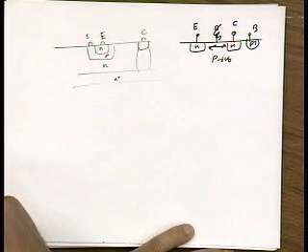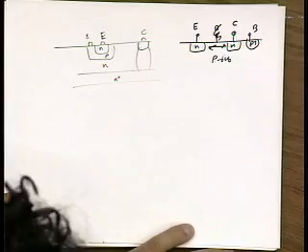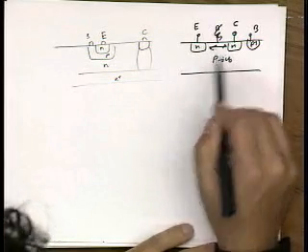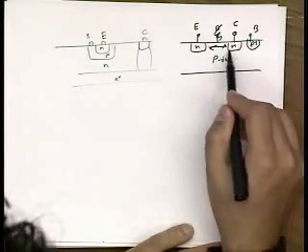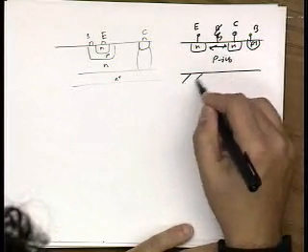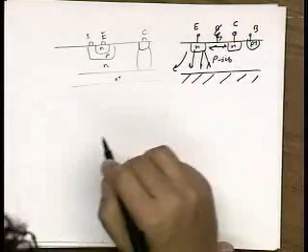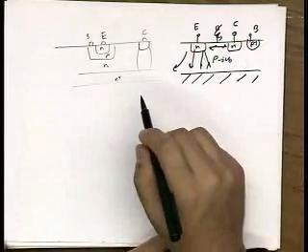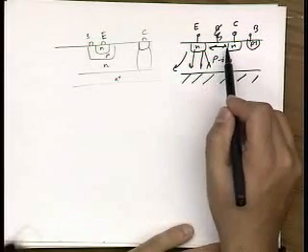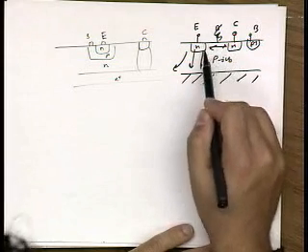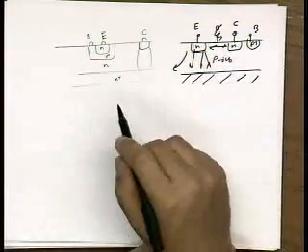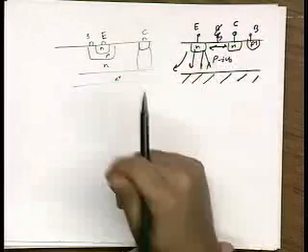Because of the alpha factors, because all the base leaks to the substrate, so you won't get a good alpha factor. That's right. So remember, when you inject carriers from the emitter into the base, what you want is you want to collect them all here at the collector. But in a real transistor, why should the carriers go to the collector when they can in fact go into this huge substrate, right, and get collected by ground? So only a small fraction of these will go to the collector unless you basically put the collector very, very close to the emitter. Now, you could argue that you could do that in a modern process. You can make these very close. So why is it that you still don't get a good transistor?